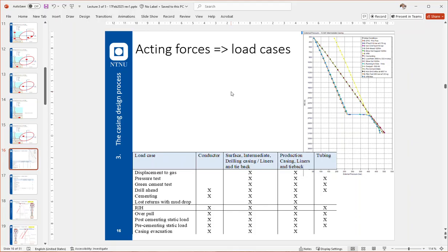It goes down to say 1 bar. And then whatever fluid, and on top of the fluid, any pressure that is in the B annulus will act as, for example, a collapse load on the casing, the intermediate casing it would be. It depends on the casing configuration, but you get the point. It's an analysis that you will do considering gas lift.